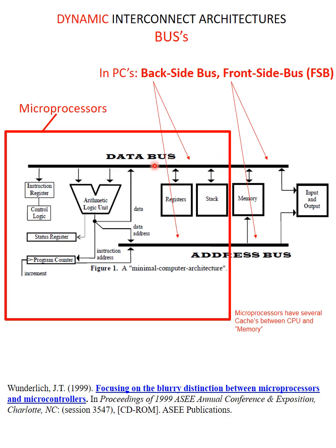And there are different clock speeds. The backside bus will be running the fastest because it's in the silicon and all the registers are right there. Once you come down and go across the board in some kind of metallization, the printed circuit board, then you're going to run at a slower clock speed, and then the memory has its own clock speed too, or access time. So you need to coordinate all that, as well as the I/O, which is shown here as memory mapped I/O, although that's not always the case.